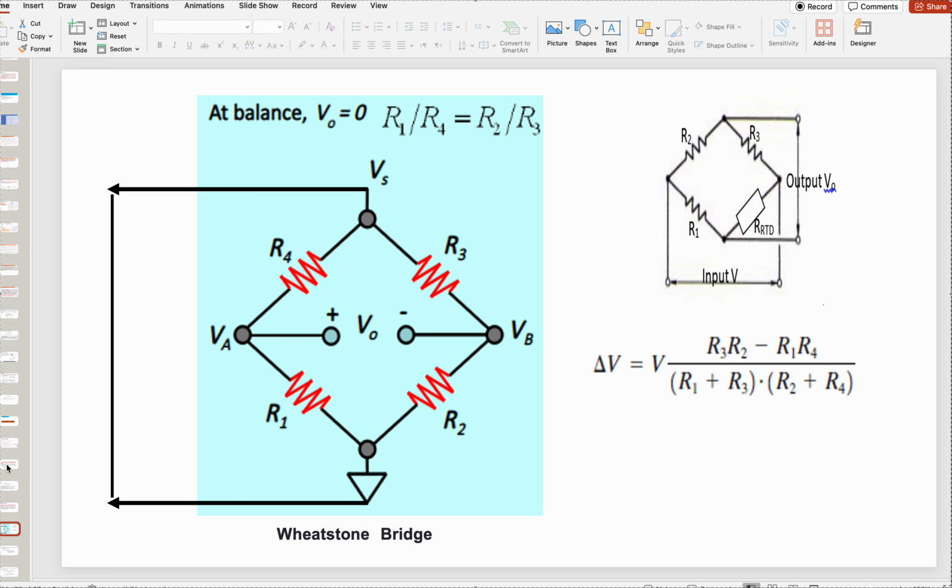The bridge circuit is another type of question that you may get in the exam, and recall that this is what we have as an equation. In this case, one of those resistors is going to be R4, for example. So if R2 times R4 is equal to R1 times R3, this is the equation.